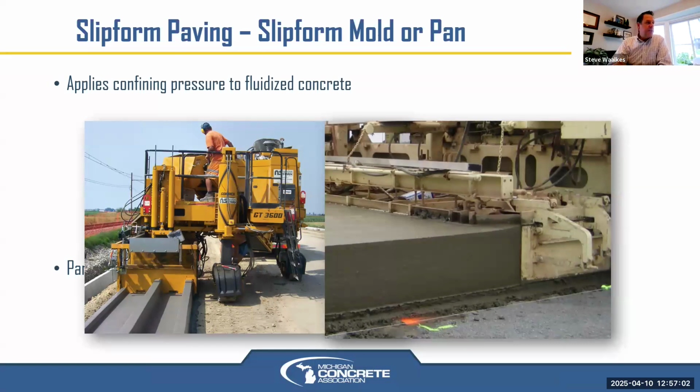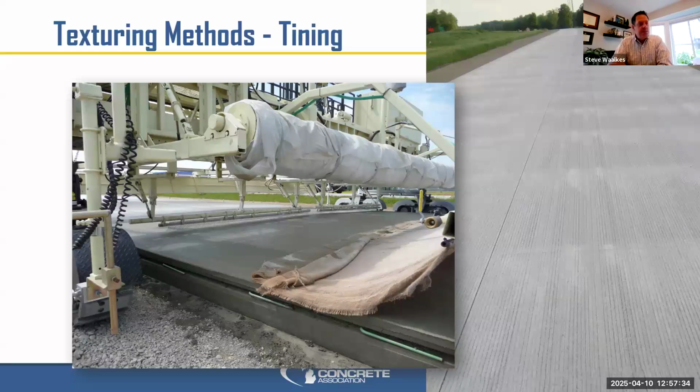Keep going. All right. As you can see, different molds: standard rectangular paving molds, slip-form barrier wall, curb and gutter molds, lots of different options. There's a very unique one on the left there that I haven't seen very much. On the one on the right, the edge of the pan actually tips up, and the side form usually has a bit of a batter to it as well to allow for a little bit of slump so that it comes out to a completely square edge, and a flat top and a vertical edge. So it's all in the art of setting up these machines.